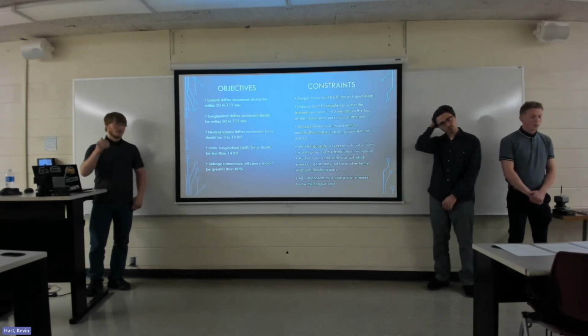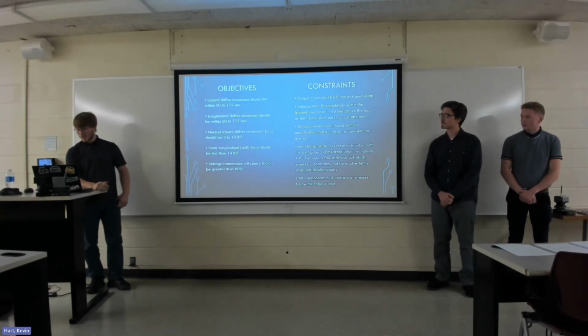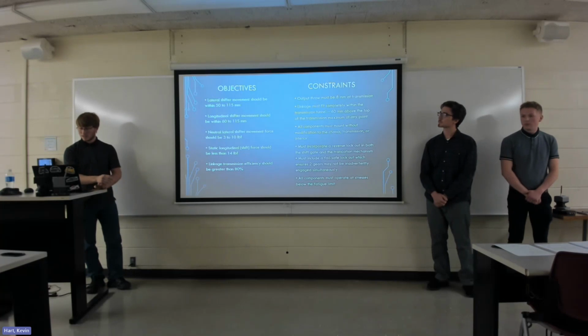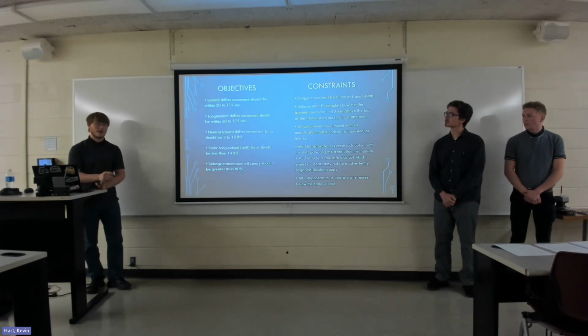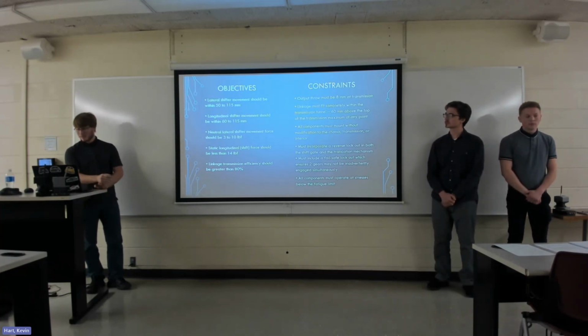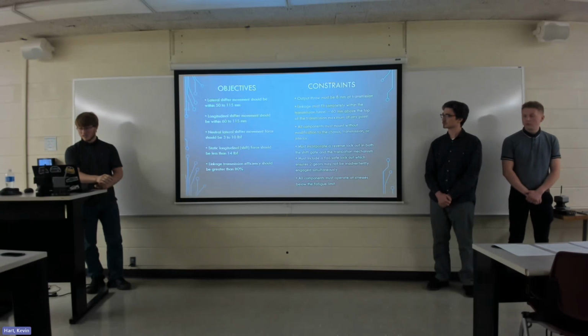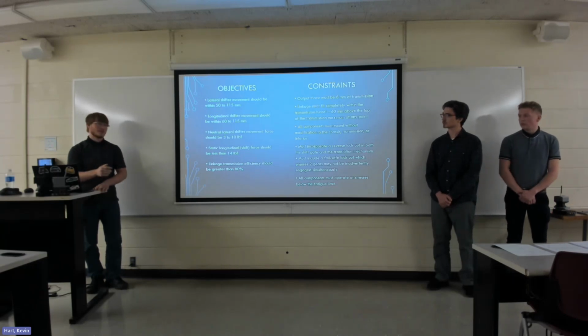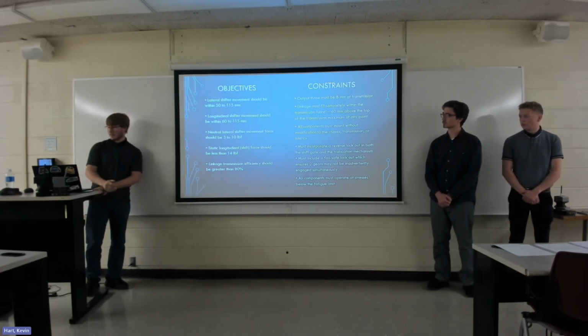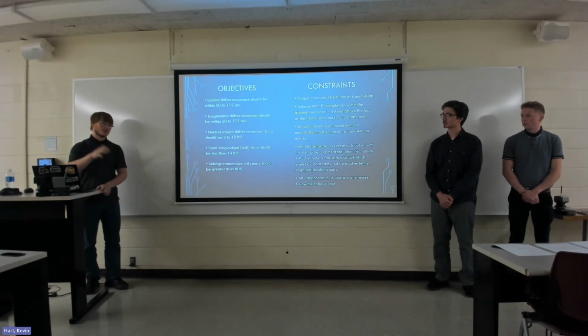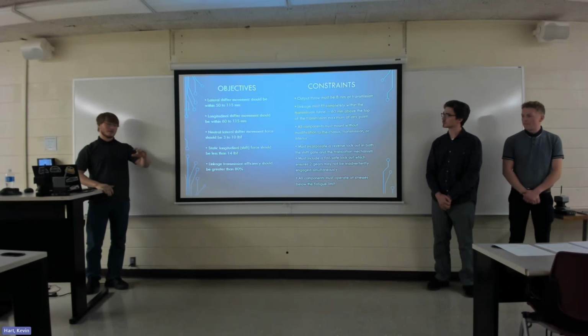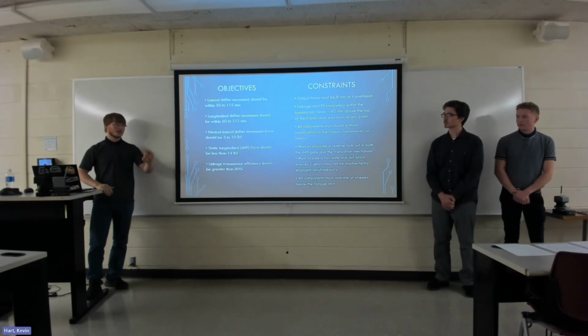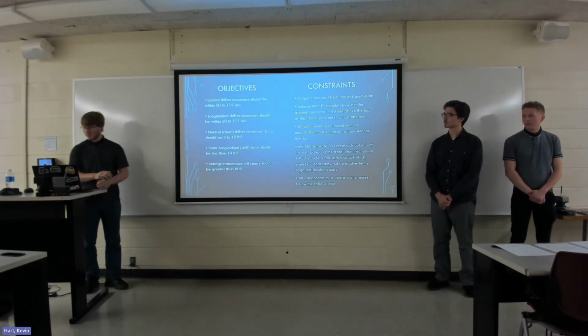These are the things we have to meet. The output throw of our transmission linkage must be 8 millimeters. This is to match the stock SMG transmission. The linkage must fit completely within the transmission tunnel. This is the area that is currently taken up by the hydraulic control unit that BMW designed.